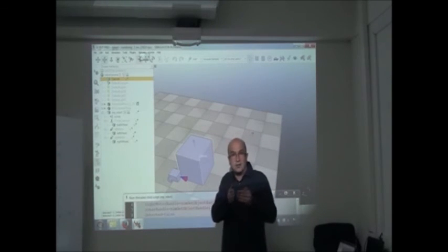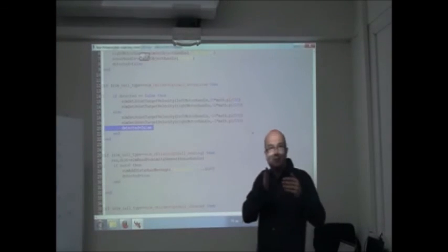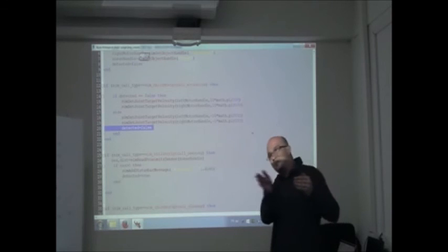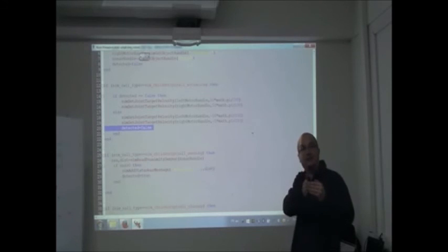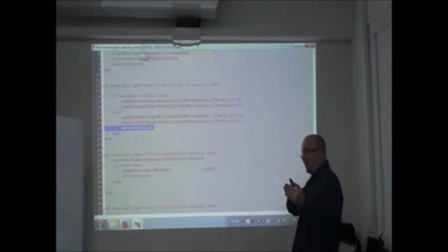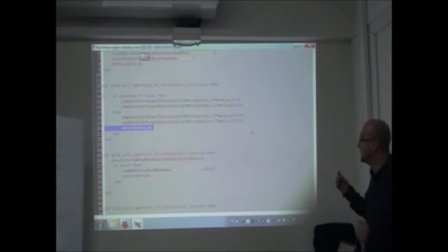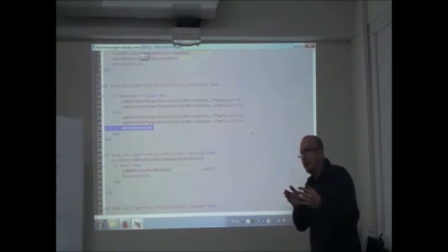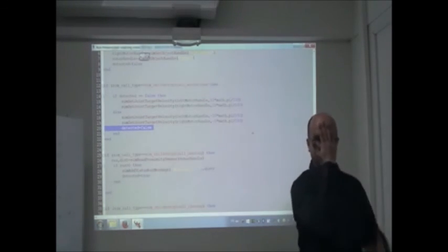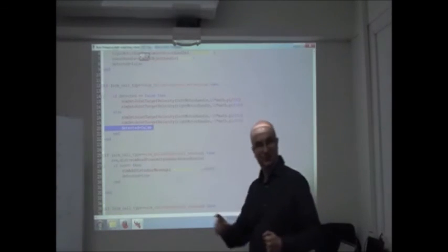Like instead of the algorithm doing the following, as soon as I detect something, you start to change your heading. But the thing is not going even backward a lot, because as soon as I go backward, I'm not detecting anything. So I go backward, rotating just a little bit. This is not enough. So maybe what would be more interesting is to put some kind of timer so that when I detect something, I go backward for a certain amount of time. Like I go straight, I detect something, I go backward and then stop for a while, and then I go front. You can do something like this.